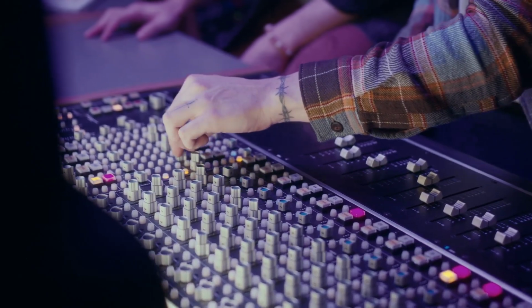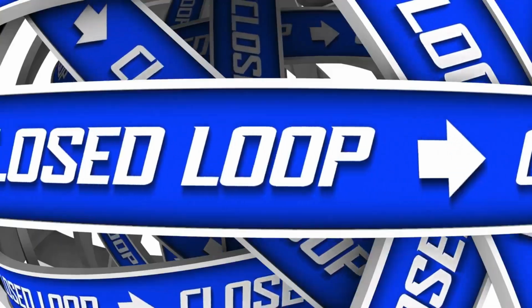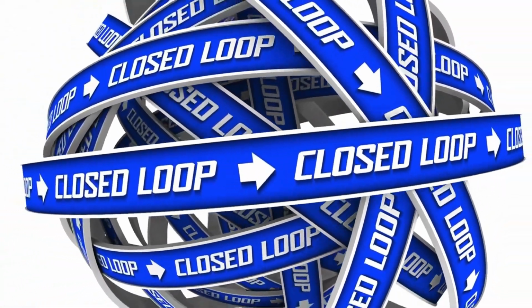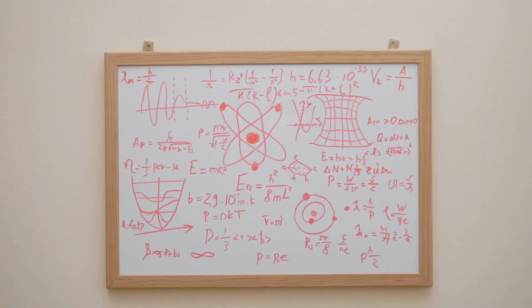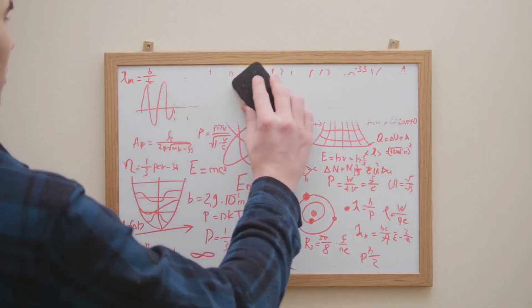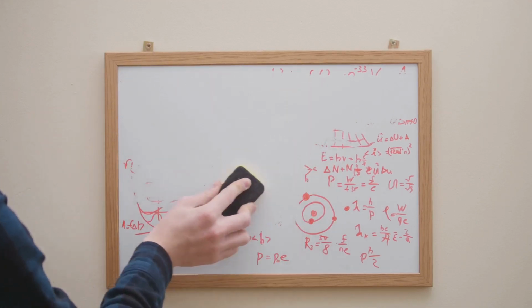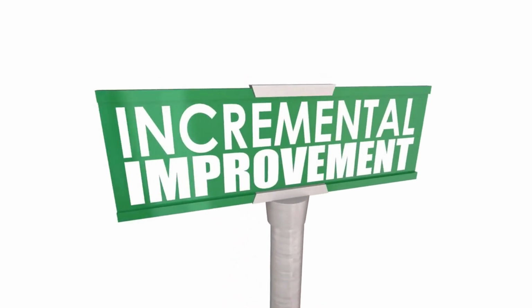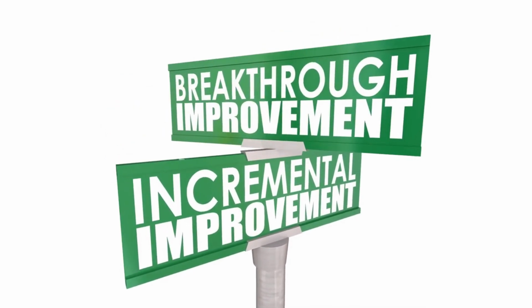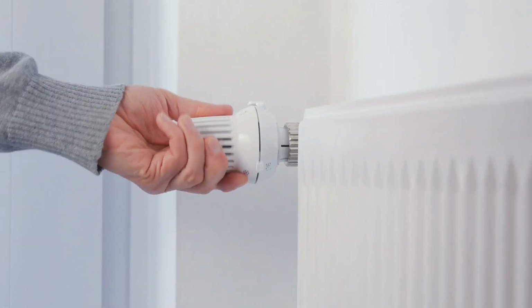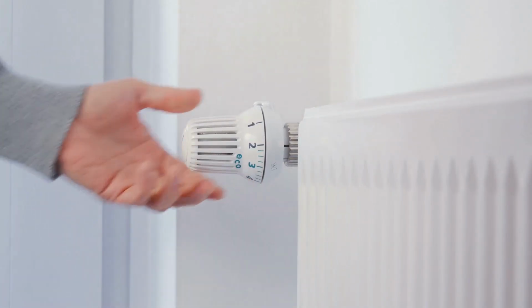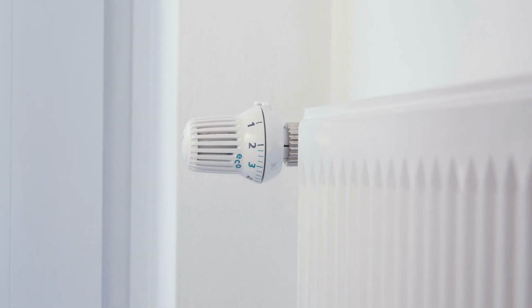With the proportional gain providing basic control, we introduce integral action to eliminate steady-state errors. The integral gain, or KI, determines how aggressively the controller compensates for accumulated errors. Start with a small KI value and gradually increase it while observing the system's response. The integral term should help eliminate any remaining offset between the PV and the set point.